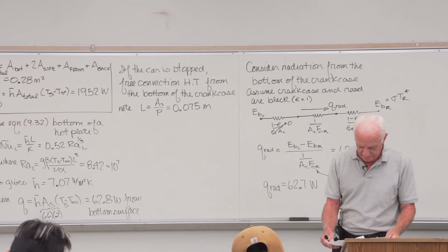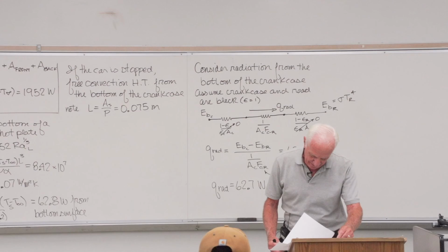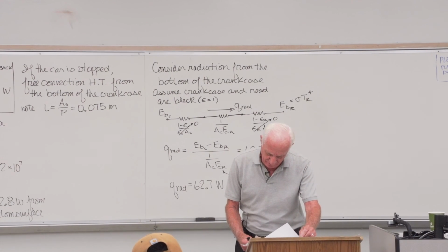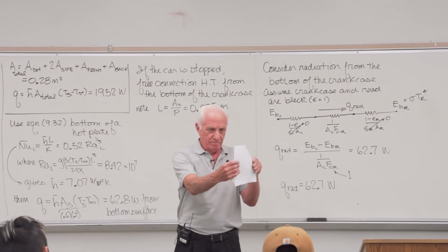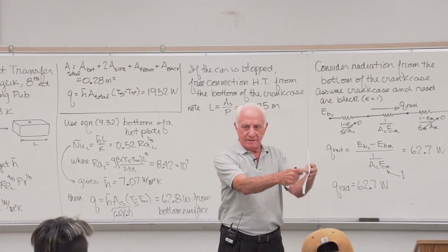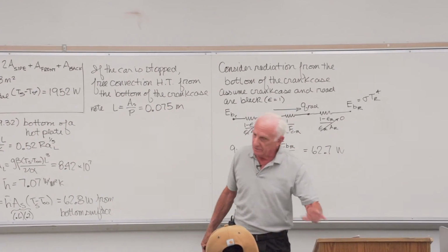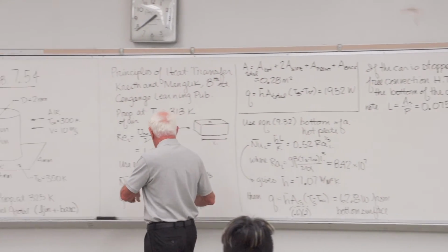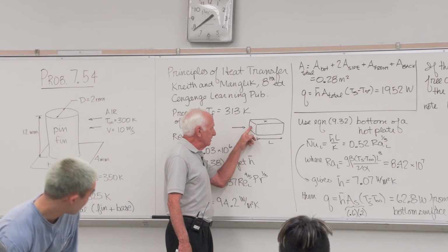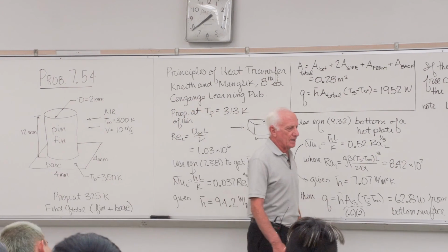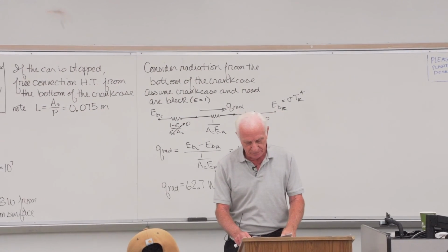And the table, I think I've got, do I have it here? No, let's see. Let's see if I've got that. Oh, yeah, table 7.3. It's for a flat plate. The picture in the book is a flat plate, just like this, and the air hitting right there, normal to the surface. So I would get another H. I would get two other H's. I'd have the H for the bottom and the two sides. Then I'd find an H for the front and an H for the back. And that's much better to do it that way than assume the H is the same on all 5 surfaces.